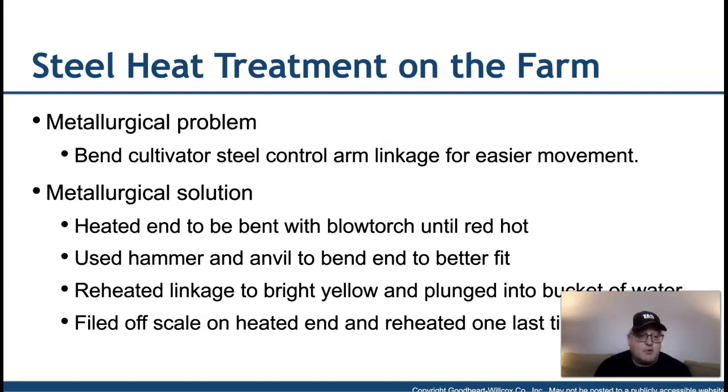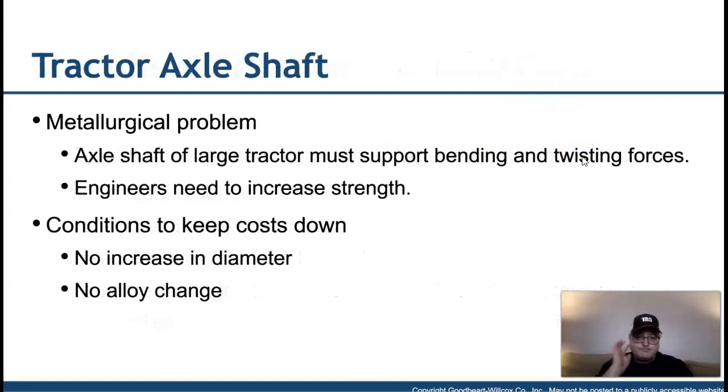So in this case, we're going to reheat that linkage to bright yellow. They plunge it into a bucket of water so they can do a quick quench. And then, of course, file the scale off and reheat one last time for stress relieving.